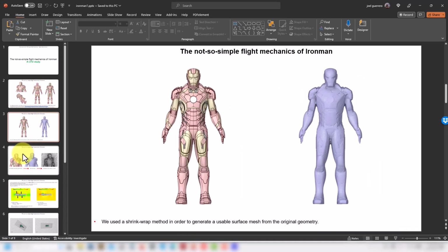So basically what we're doing is that we're taking our geometry, with all those features, but we're using a method that is called thin wrap. Okay, so basically what we do is create a surface mesh of this complete geometry, and we aim at capturing the main features, and then we decide what is the level of resolution that we have. So now that we have this surface mesh, which can be any format, probably you're already familiar with the STL format. This will be our input for our meshing tool, okay?